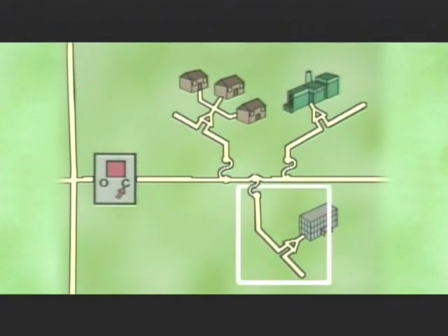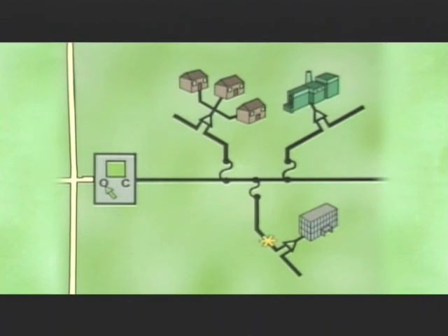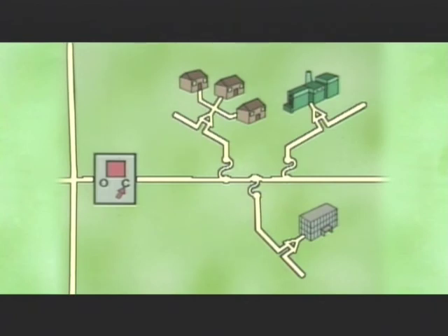However, if a fault occurs on one of the laterals, slightly different events take place. When the fault first occurs, the circuit breaker will sense it and open. If the fault clears, service will return to normal when the breaker automatically closes. However, if the fault remains, the circuit breaker automatically shifts to a different mode of operation. The second time the circuit breaker senses the fault, it delays opening for a short period of time. The actual amount of delay varies from system to system. Regardless of the system, however, the delay provides enough time for the fuse connecting the lateral to the feeder to open.